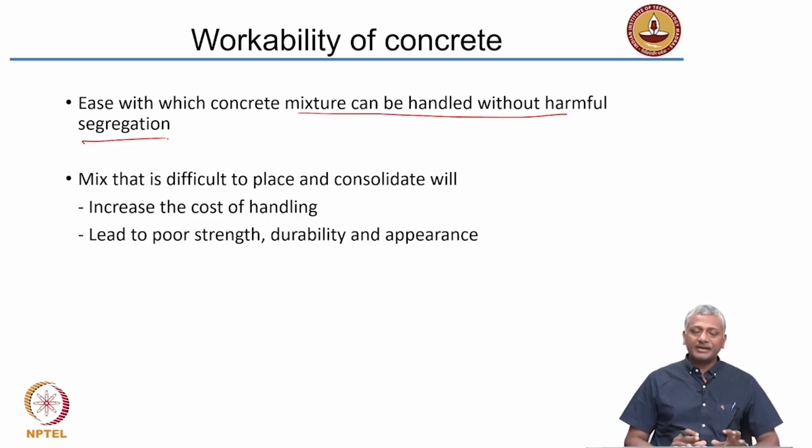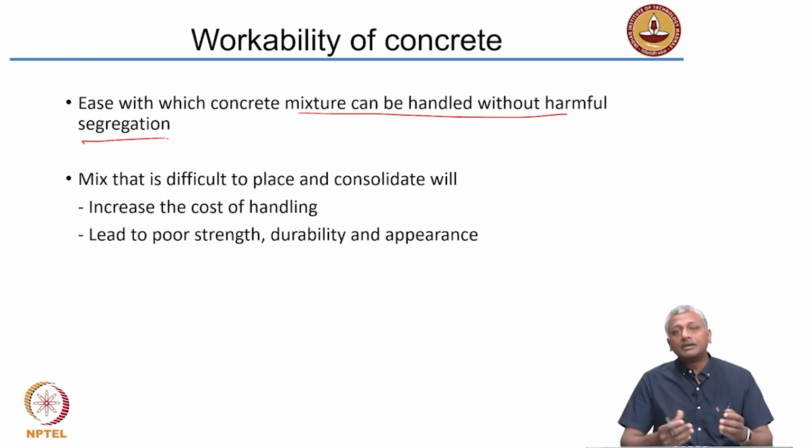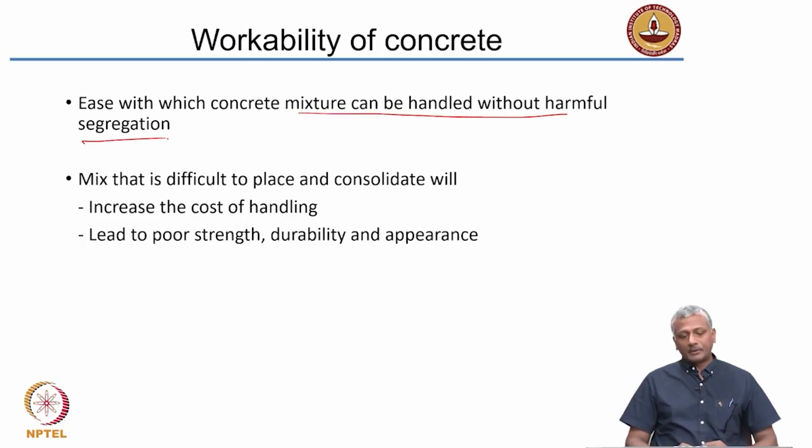So, workability is defined as the ease with which you can handle the concrete without causing segregation. Okay. Now, a mix that is difficult to place and consolidate will increase the cost of handling and also lead to poor performance in terms of strength, durability and appearance. So, you need to provide concrete of the right level of workability. It is very important that you do so.